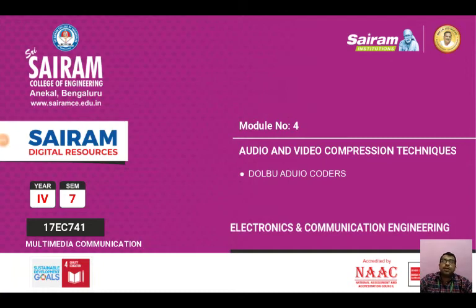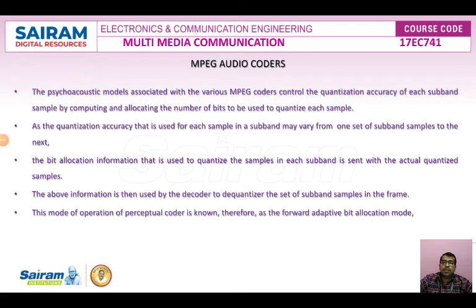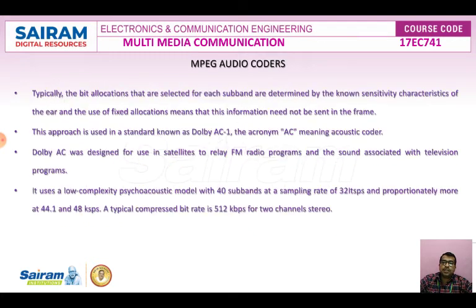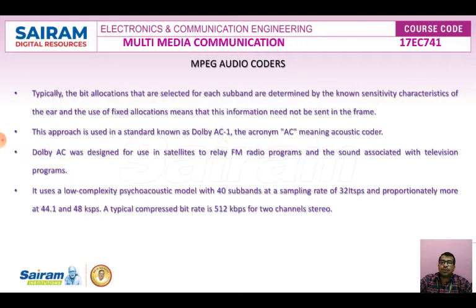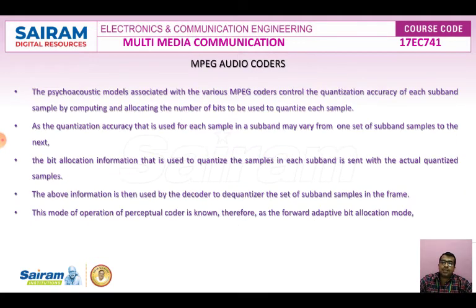Dolby audio coder and MPEG audio coder, two things will be considered here. Dolby audio coders are also similar to the MPEG audio coders. It is a kind of MPEG audio coder. Here the psychoacoustic model, which is associated with the MPEG coder, will control the quantization